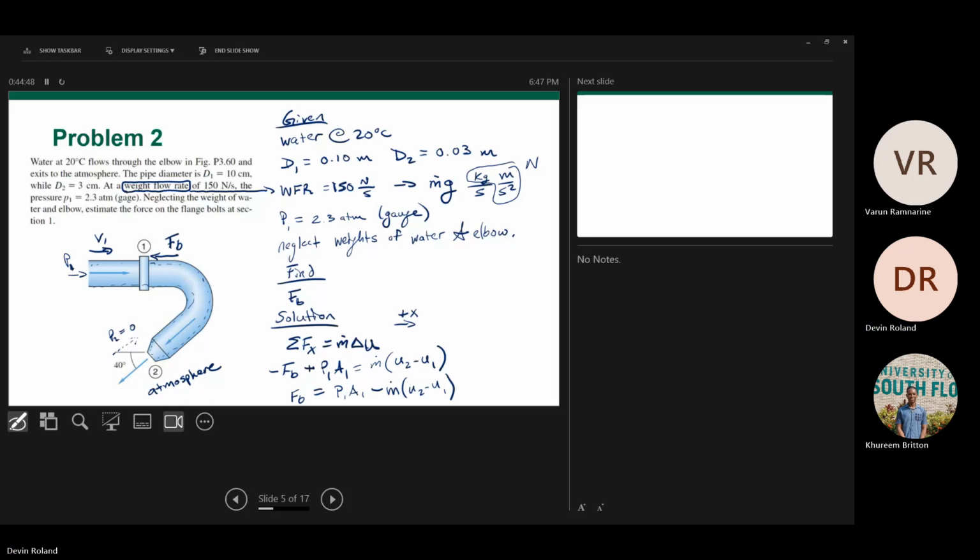And so the bolt there is resisting the pressure, like ripping the system apart. So if we had assumed that force to be in this direction, let's say, we would have gotten a negative value. And that negative value would have told us that this assumption was wrong. And it's actually going to the left. Does that answer? Is that kind of what you're getting at? It helps me understand what you were saying there.